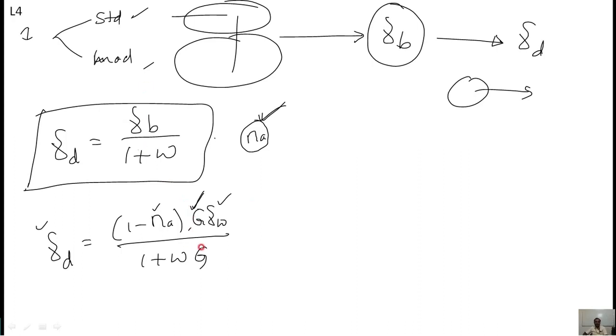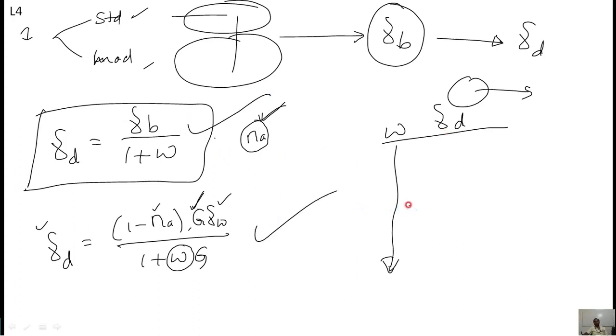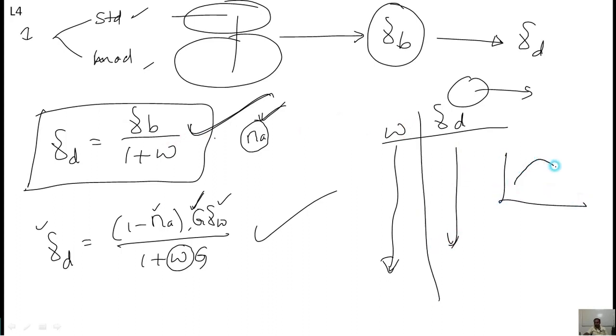Okay sir. Then what is left here? You want w, means everything is known, no? Then you know the water content variation. By using this water content variation, you can get gamma d. To get gamma d, you have two equations, either this equation or this equation. Now, if you use this equation according to Proctor and write the gamma d, then you will get a graph this way.